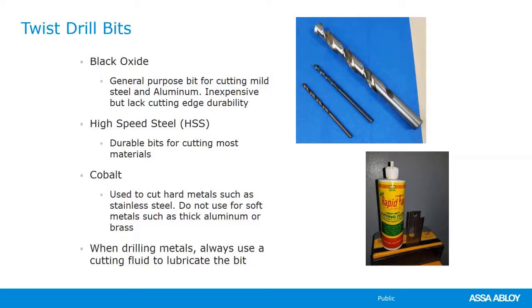I know a lot of technicians that really hate putting holes in stainless steel, and it's more than likely because they're drilling too fast. The RPM is too fast and they're not using a cobalt bit. So definitely have to have different drill bits for different applications in your bag, and always use a good cutting fluid. Now, most cutting fluids are either petroleum based or synthetic oil, but you can also get cutting fluid that is water based.